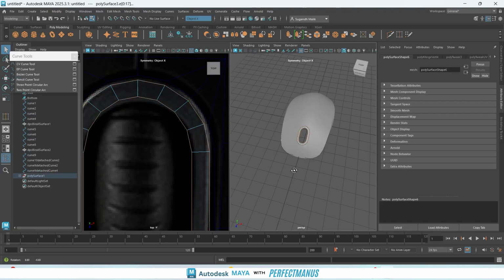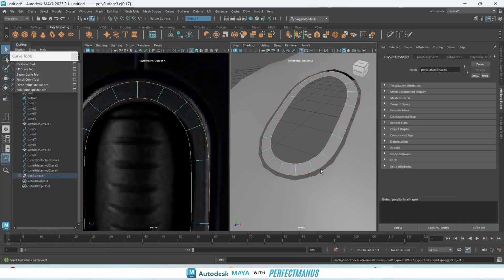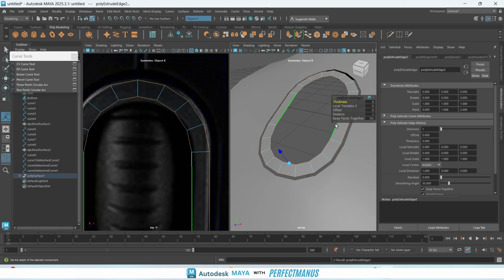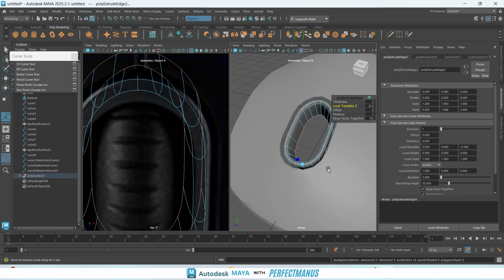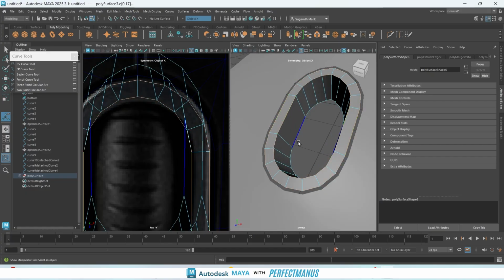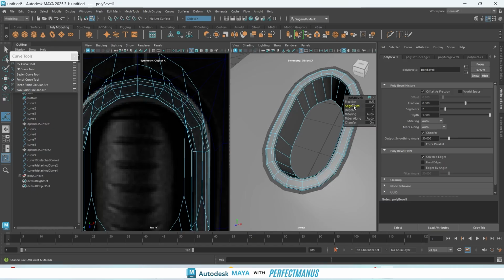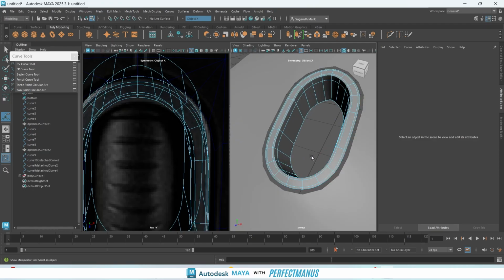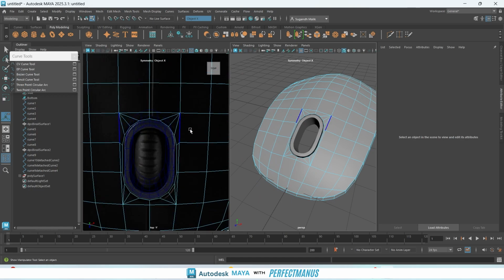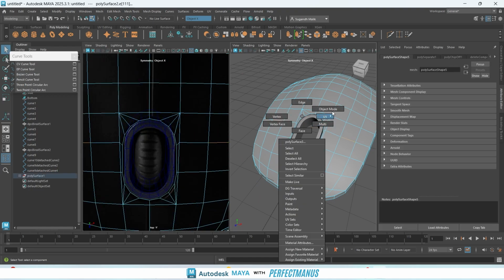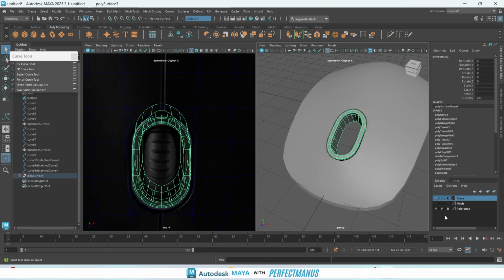It's like this and this, and we extrude it down the z-axis. So when we smoothen it, it will be something like this, but we want your edges to be sharpened. So you bevel it, you increase the segments, you decrease the fraction value. So when you smoothen it out, it will be left as is. Similarly for this one, we can do it, but first we need to make sure it's hidden, because it's getting in our way.